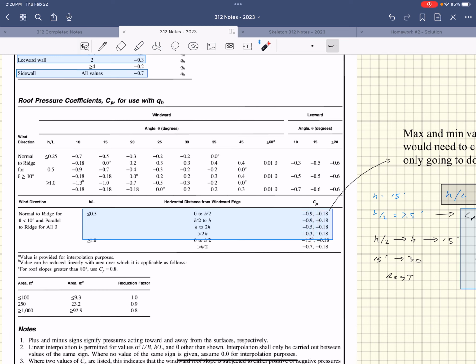Technically what that amounts to is two different load cases, right? And so there's a maximum amount of pressure and then a minimum amount of pressure. That has to do with sometimes a minimum amount of pressure will actually control the design of certain elements. Actually, the internal pressure that's pushing on the thing, or the uplift, could actually help you.